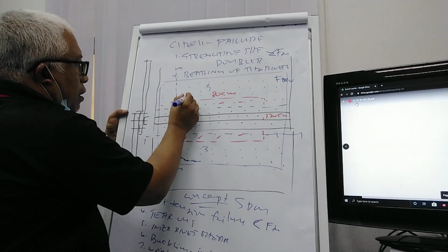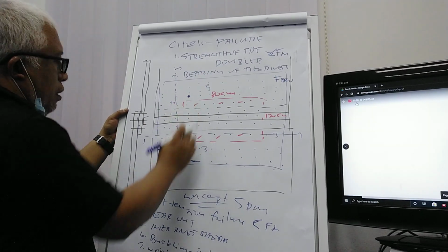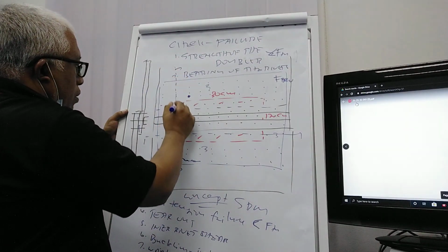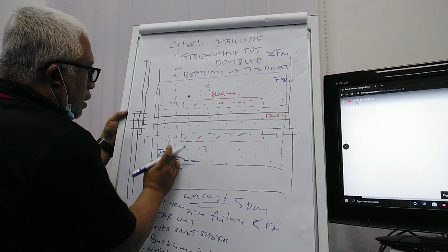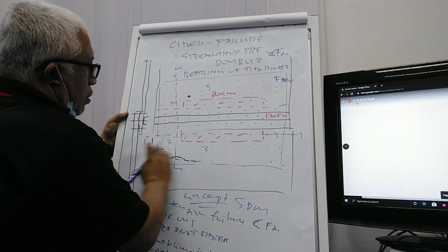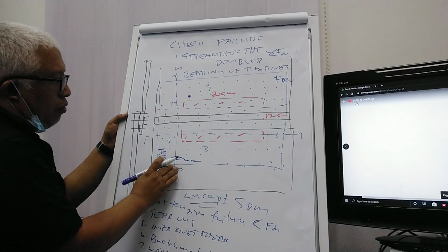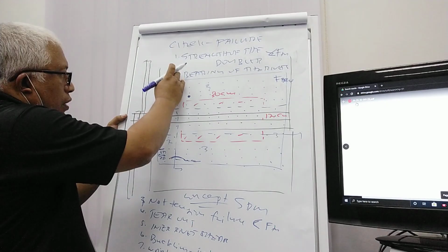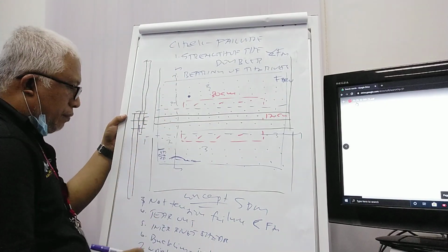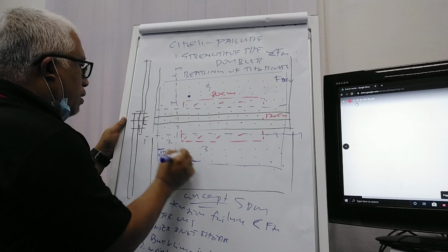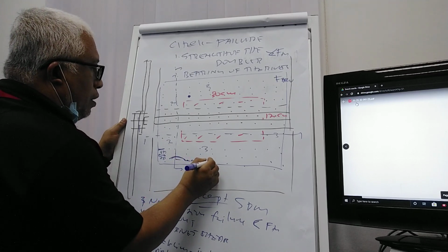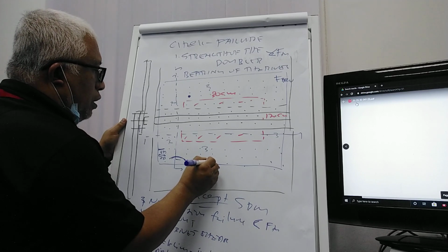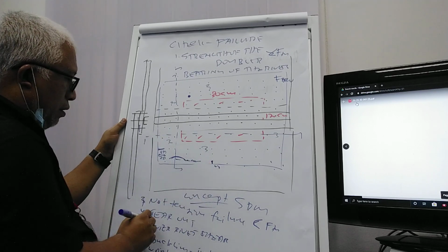Then bearing in the rivets, and you check the net tension, the failure as you cut across here through the fastener rivets, whether this area that we cut across, with the load that we calculate later, will be able to stay without failure, without cutting off or cracking across. Then tear out is why we should have enough edge distance from the fastener to the edge, because potentially the rivet migrates out. They call it tear out.